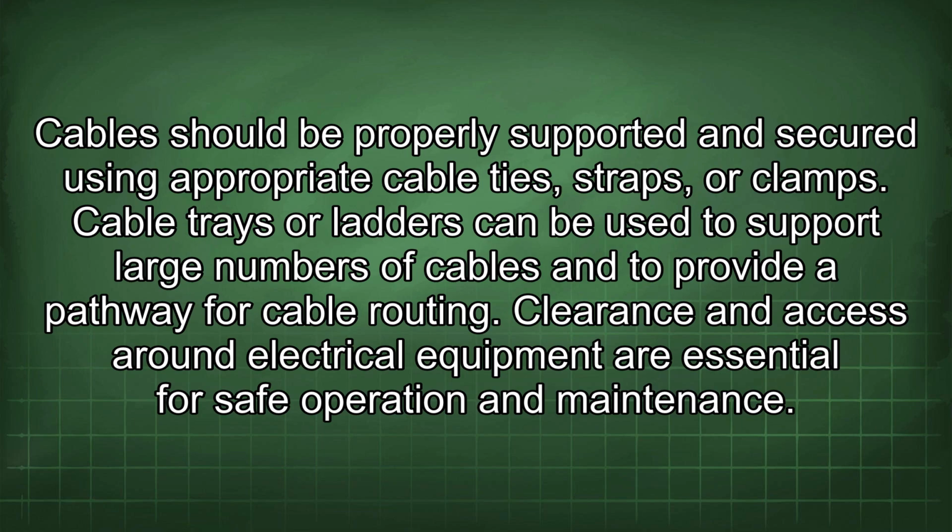Cable should be properly supported and secured using appropriate cable ties, straps, or clamps. Cable trays or ladders can be used to support large numbers of cables and to provide a pathway for cable routing. Clearance and access around electrical equipment are essential for safe operation and maintenance.